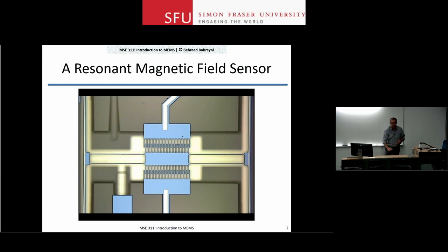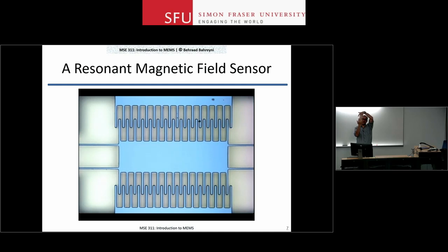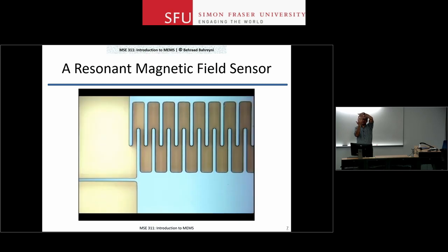And in this case, they are electrostatic actuators. They are combs. And what I'm doing is that I'm applying a voltage to the bottom electrode. The voltage difference between the bottom electrode and the moving part, the shuttle part, will attract the shuttle towards the bottom electrode. If I apply an AC voltage, well, this starts to go up and down, as you can see in the video. Now, one thing that I should remember is that the force was proportional to V squared.